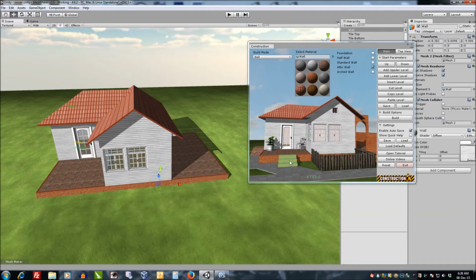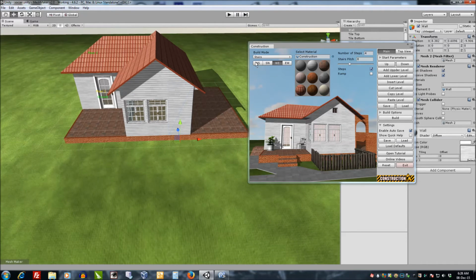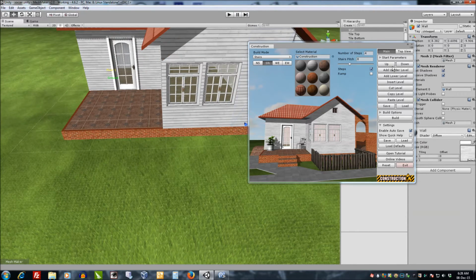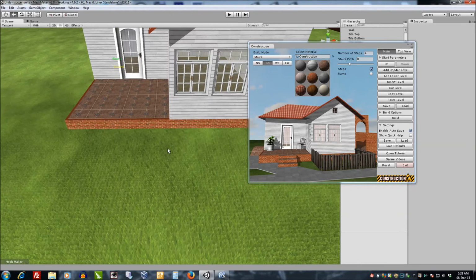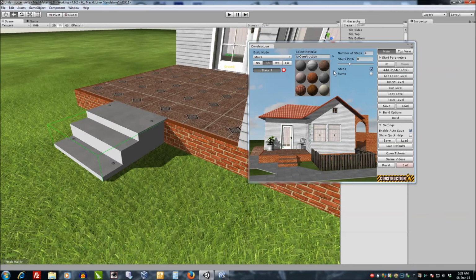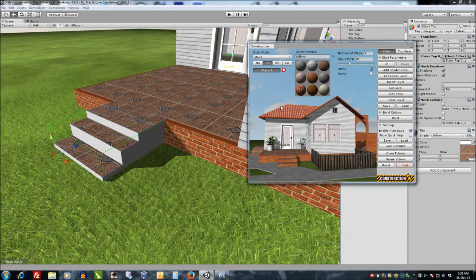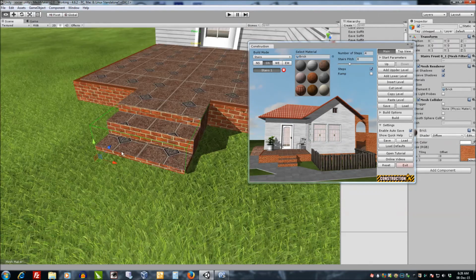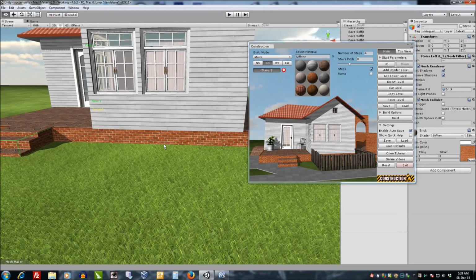And we'll do the stairs now. Stairs work very much like roofs. The direction here, the north-south, south-north, west-east, east-west, that's the slope of the stairs. So if we want stairs to go this way, we'll choose south to north. Move down to the ground level here, and add that there. You can paint those, and you can also paint the sides like that.